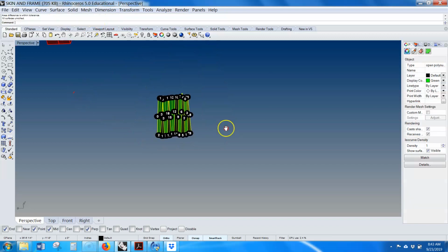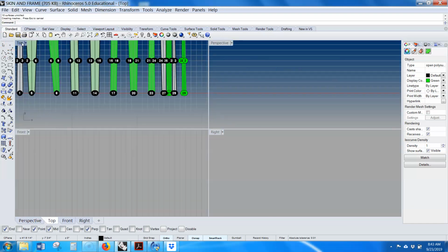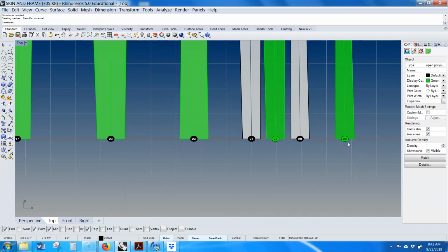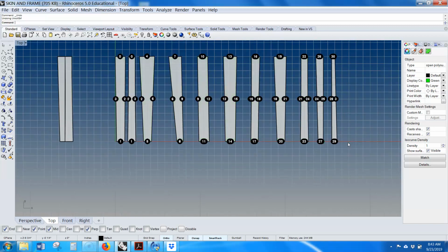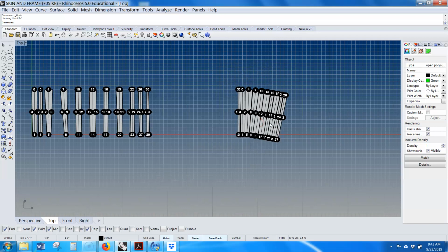Something to keep in mind when you're doing this. Be careful, because sometimes I didn't have key properties selected. Sometimes it will slightly change the scale of these things when it's unrolling them. So you may want to go back in and just measure one edge. Probably the ends are not twisted, and make sure that the ends are the same scale. Just to make sure. Otherwise, if they're sized differently, they might not fit together. Okay, so everybody got unroll?